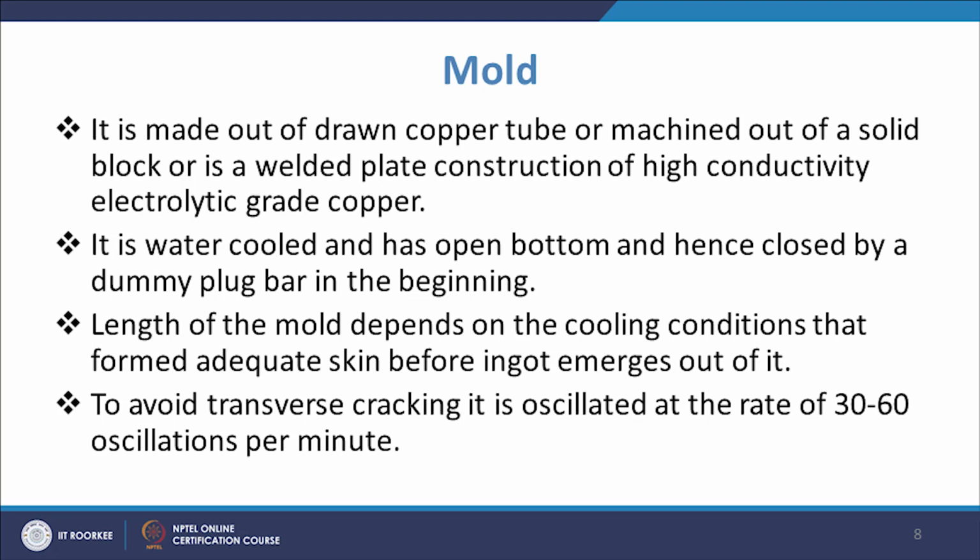But as we discussed, since the melting temperature of copper is lower as compared to that of steel, we need to have another cooling mechanism constantly, so that it can take the heat away quickly and should not melt. For that it is normally water cooled and has an open bottom, and hence is closed by a dummy plug bar in the beginning.